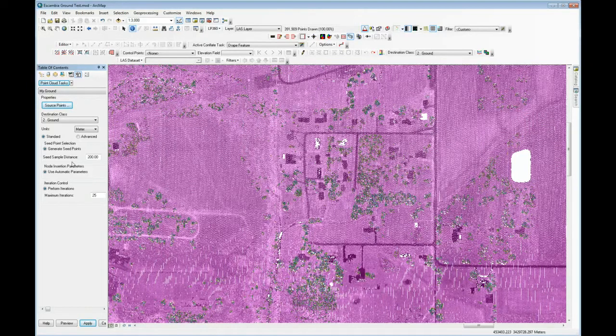I'm then going to look at all of the rest of the points in an iterative process and see how well they will fit into this initial TIN, and that's why we call this algorithm an adaptive TIN. There are 2 parameters that I use when I do that test. The first one is how far is the candidate point from the TIN, and if it exceeds a threshold, I won't say that it belongs to ground. And the second one is that if I included it in the TIN, I would have a new TIN face or facet. And what angle will that new face make with respect to the existing TIN? And if that angle exceeds another threshold, then I'll say it's probably not ground. So those are the 2 tests that I make.